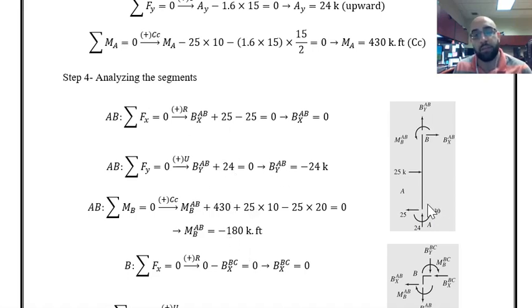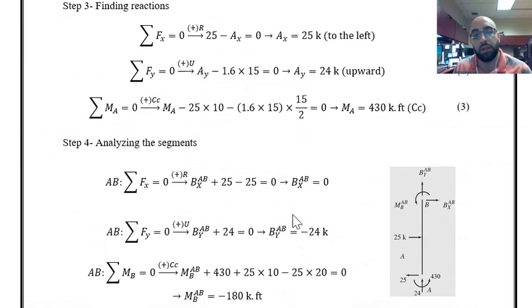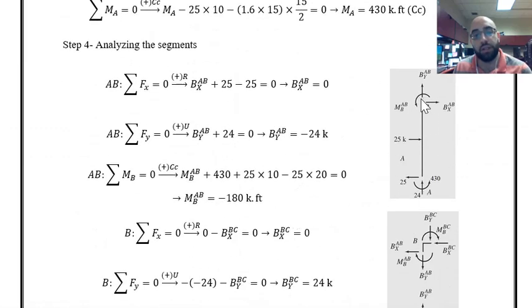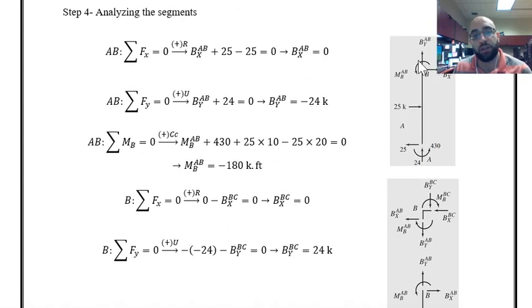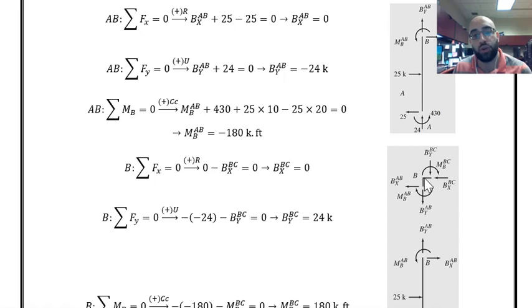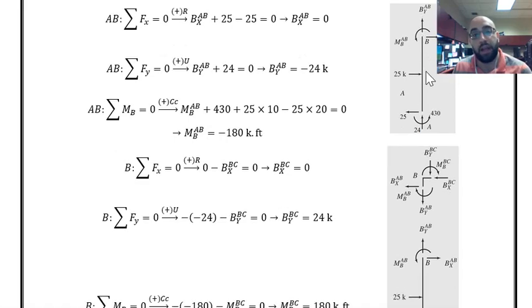and we have these steps in terms of the calculation. We have member AB. These are the reactions that are coming from support A over here. So based on those, I could find the forces at the end B, and then I just consider the reaction of these forces at joint B, as you can see over here. At first I didn't know these forces, so I just assumed something at end B and then applied the reaction of these on the other side of B at joint B.